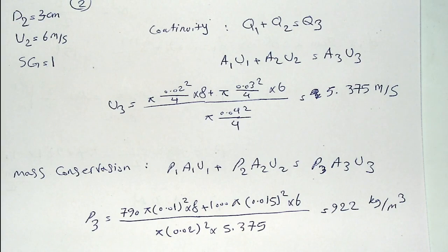So we have a tank filled with air. The initial density and the pressure are given to us. And then this tank is being evacuated by the vacuum pump. So the volume of the tank is constant and is equal to 1 cubic meter, but the density of the air inside the tank is changing as we evacuate air. And then it says that the pump evacuates 0.0013 cubic meter of air per second regardless of the pressure. So we have the Q of the outlet.